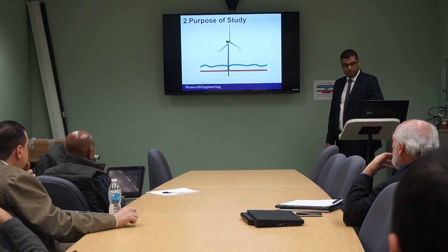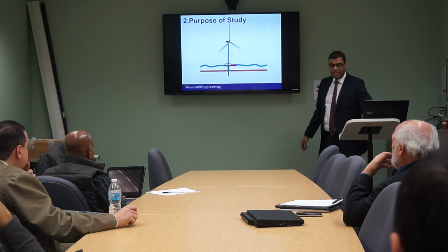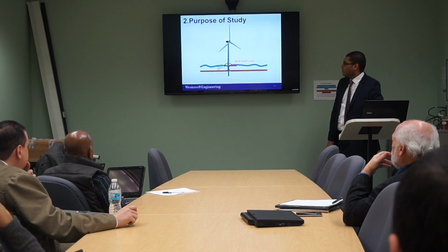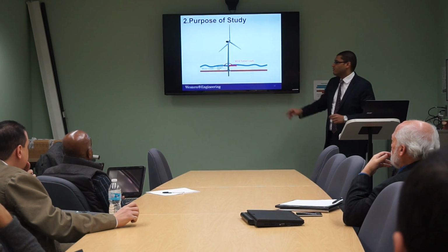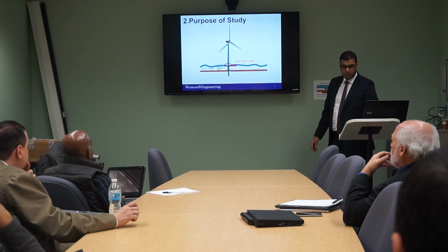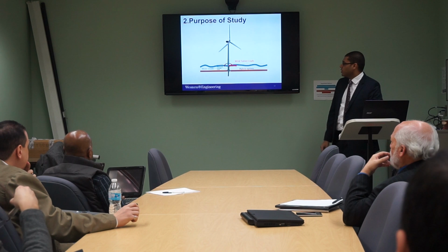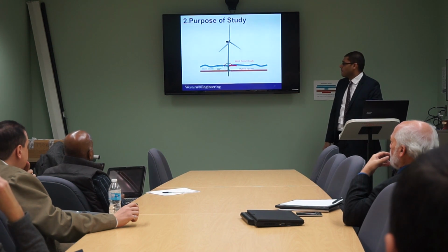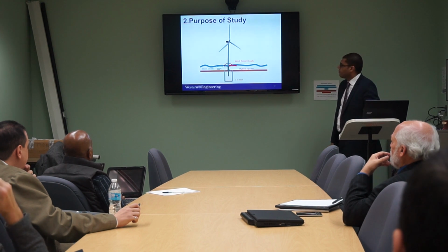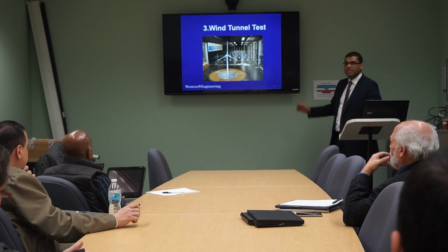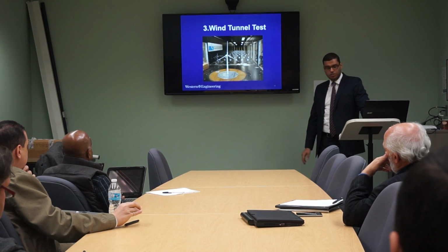Through our work, we will start by getting the load at the wind turbine. We will get this from wind tunnel loads. The wave loads we didn't calculate; we took them from an NREL report for the same case, for the same water depth. Then our hybrid system will be studied as a parametric study using the Abaqus program for different cases. Then the 1G test in the structural lab. So, the wind tunnel test. We have done the wind tunnel analysis and boundary layer wind tunnel test here at Western.